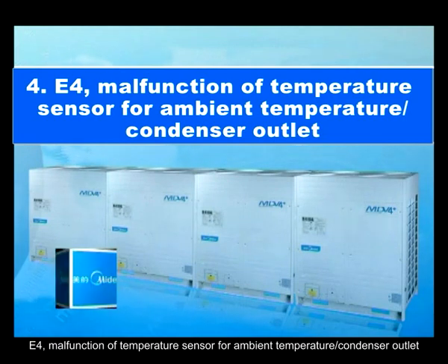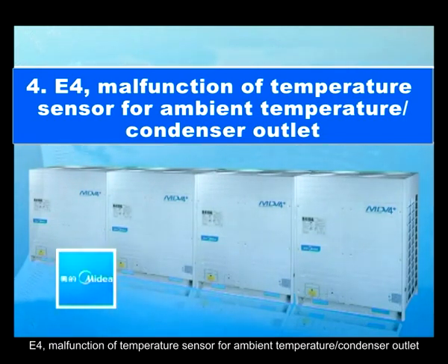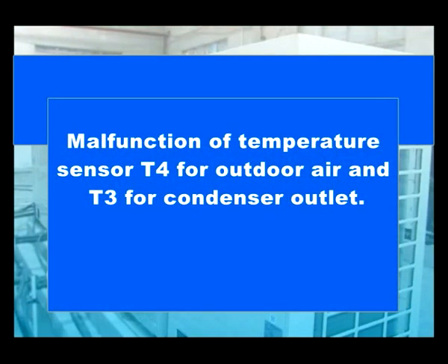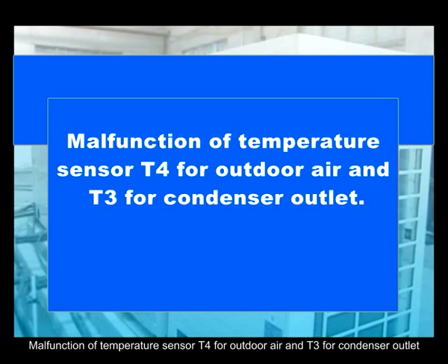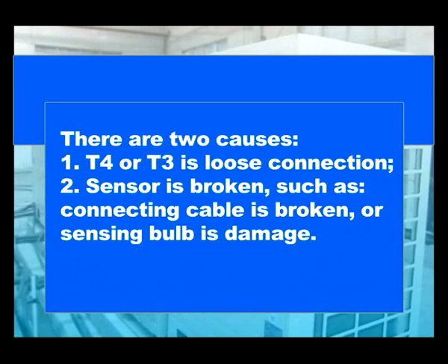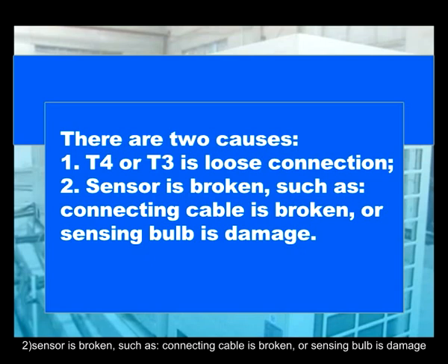E4. Malfunction of temperature sensor for ambient temperature/condenser outlet. Malfunction of temperature sensor T4 for outdoor air and T3 for condenser outlet. There are 2 causes. 1. T4 or T3 is loose connection. 2. Sensor is broken, such as connecting cable is broken or sensing bulb is damaged.